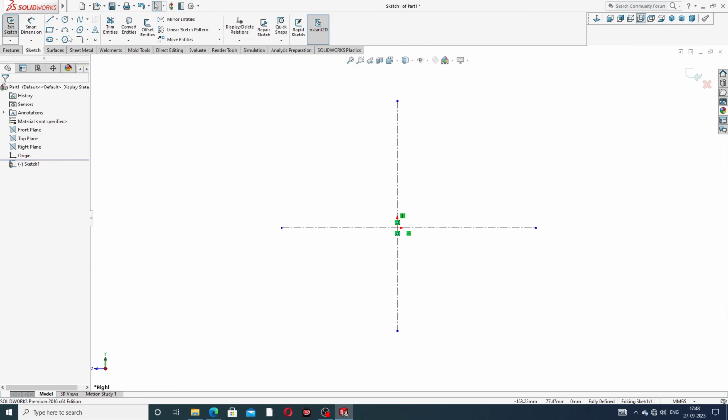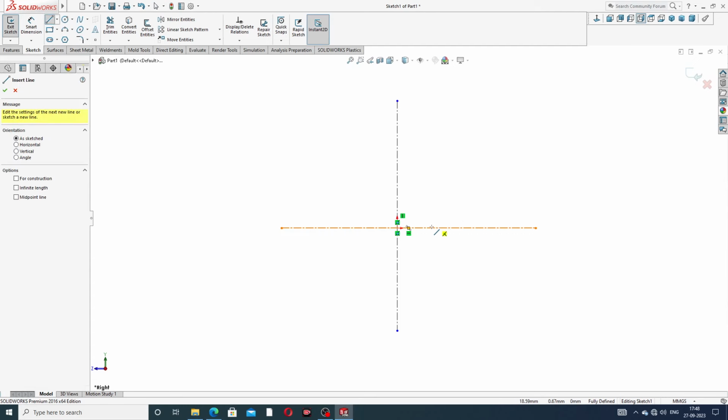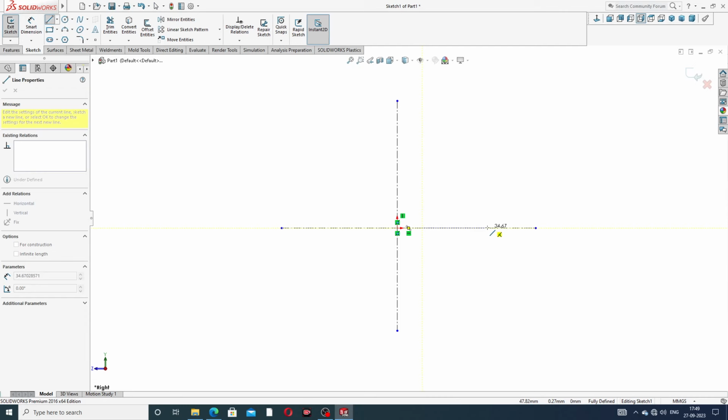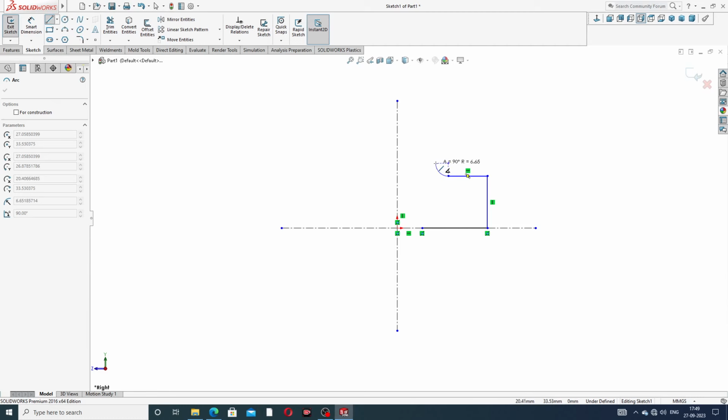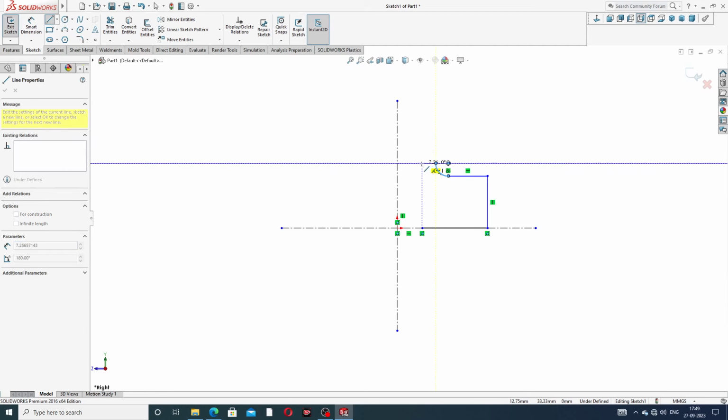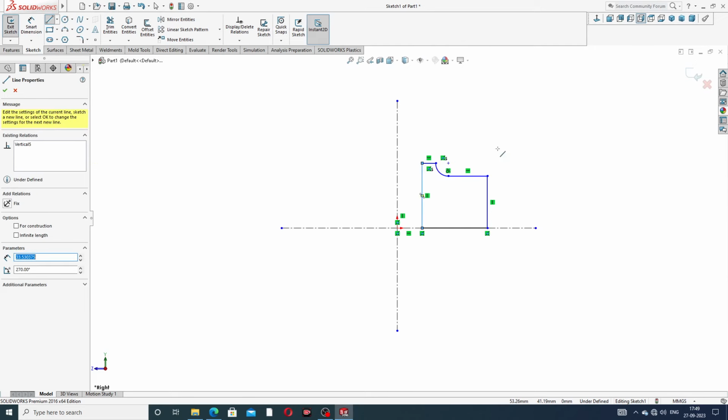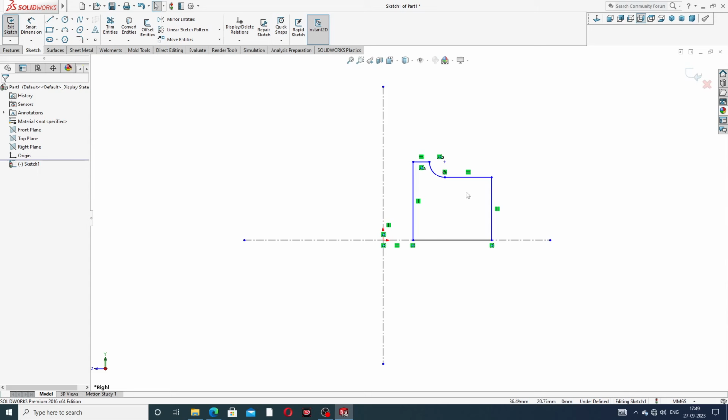Okay, and at first select a line and draw this. Perfect and correct. Then draw this geometry, and this curve is drawn here. Select a horizontal line, and this connects to this, and this is very important. This is a simple geometry drawing here. Then use align dimension.